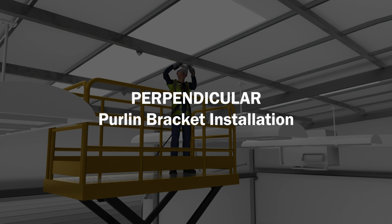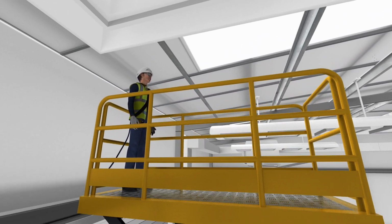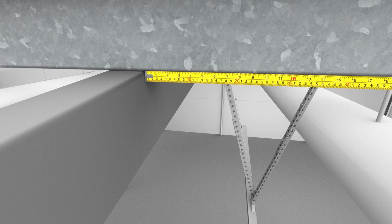Perpendicular purlin bracket installation. Create a datum point from a wall or a feature of the building to establish the center line for the rigid rail. A datum is a physical point or position that you decide, serving as a reference or base for the measurement of other values.